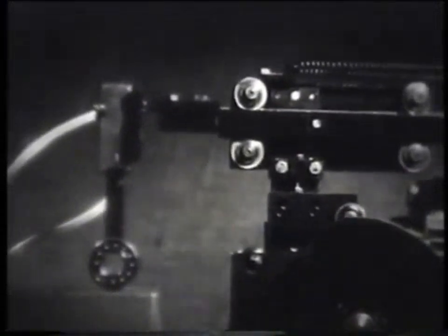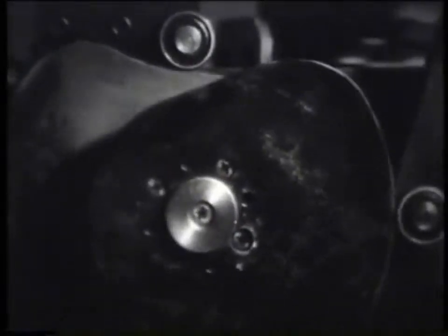To drive the manipulator of a modern robot, 2 cam mechanisms with translationally moving and swinging pushers are used, which provide 2 grip movements. These movements are set by 2 cams. Only output links are specified in kinematic schemes of robots.